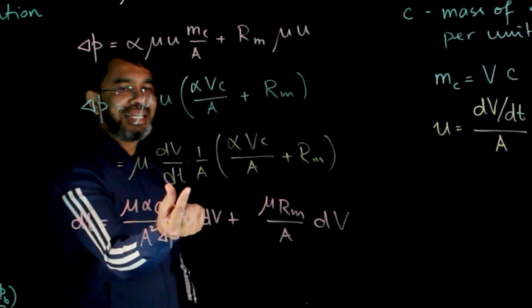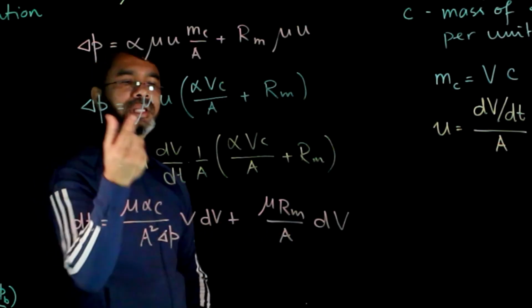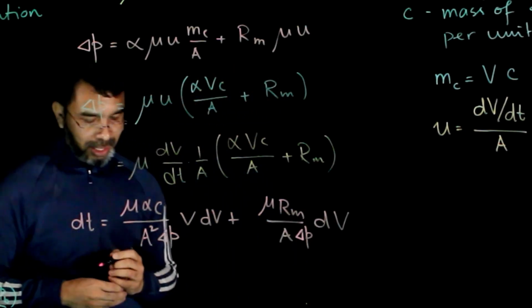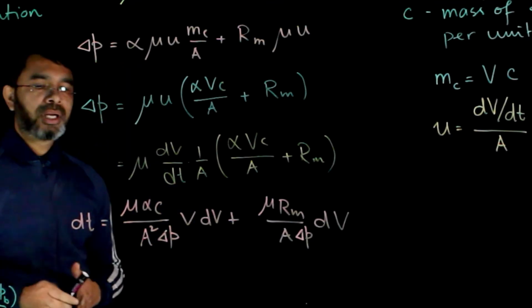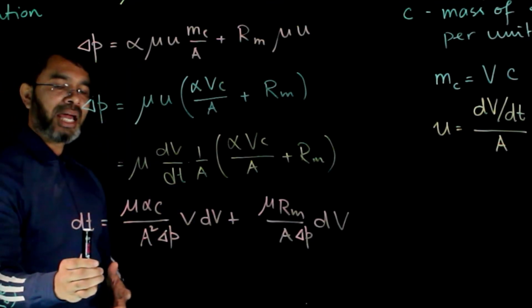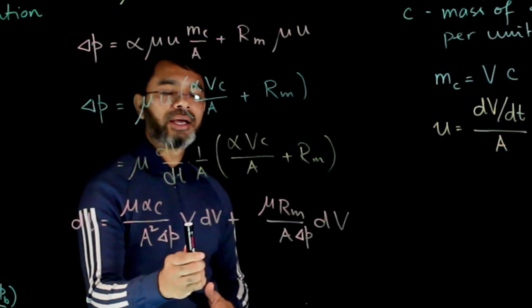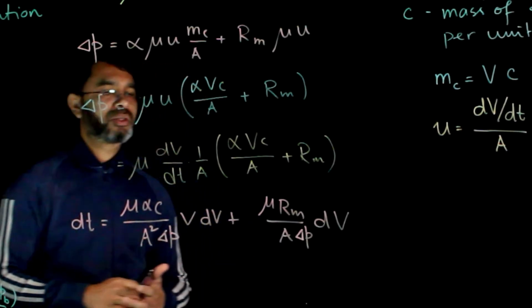So just taken this dt term on the left side, all other terms remain there, and we took the delta P term, which should be here, the delta P term on the right-hand side. Now we have done it just to do the integration. Now we integrate this for time 0 to t, and at time t, if the volume of the filtrate is V, we can integrate this equation.